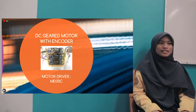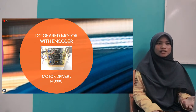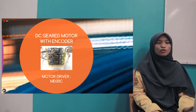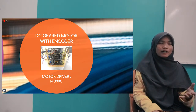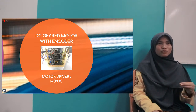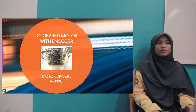For the actuators, we are going to drive the mobile robot using 3 DC gear motors with encoders, and the motor drivers that will be used to control the speed and the directions of the wheels are MD30C. We are going to use the MD30C motor drivers because of their high peak current, which can withstand 30 ampere for the mobile robot.